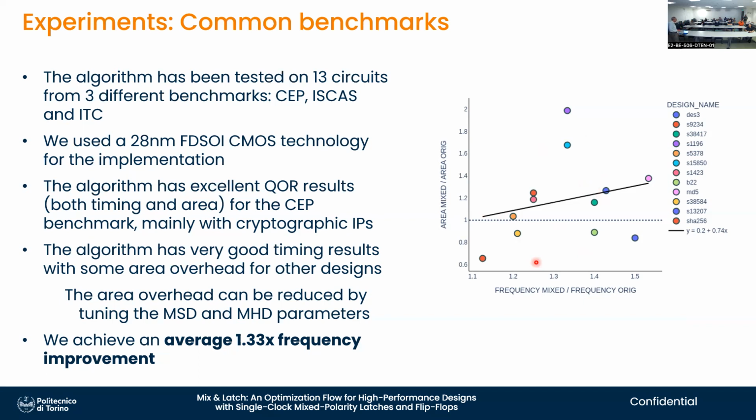And we notice that, of course, if they are acyclic, we get better results because time borrowing works very well with acyclic circuits. If you only have to get to the final destination within an hour, you can optimize things a lot along the path, while if you have to run in circles and make it on time at every lap, things are more difficult. So for cryptographic circuits, which are typically acyclic, we get excellent results.